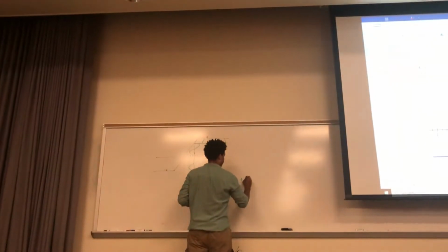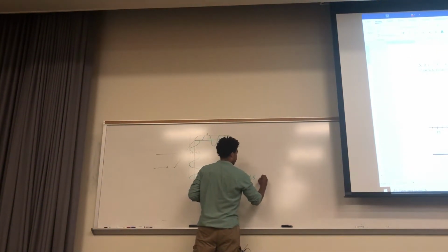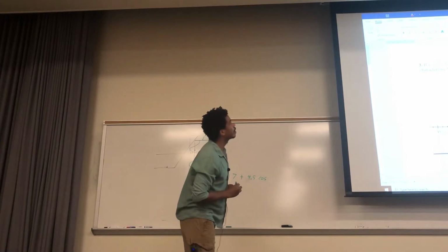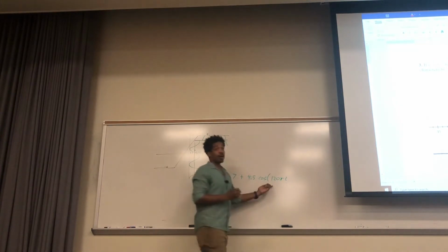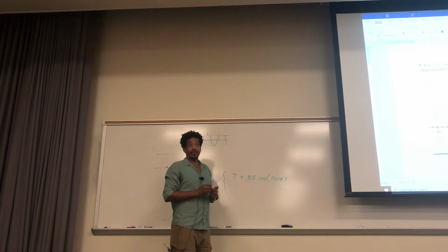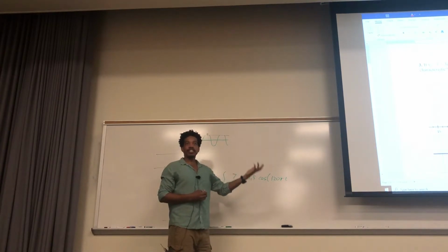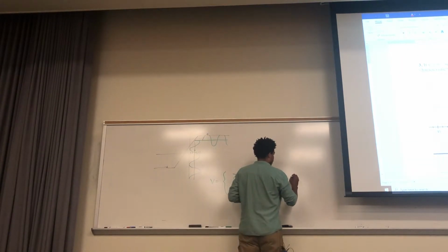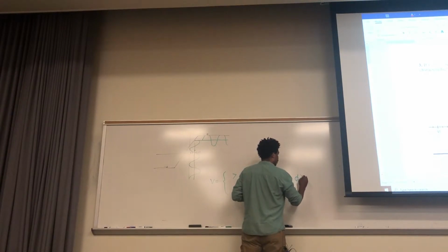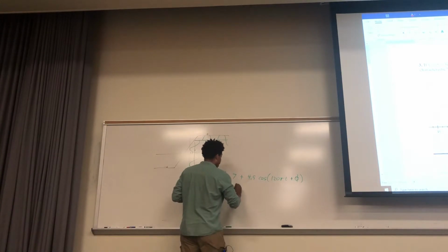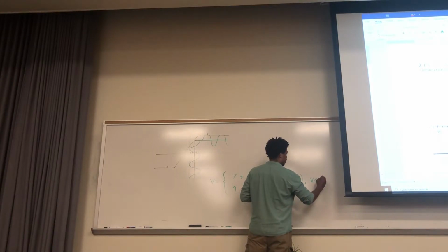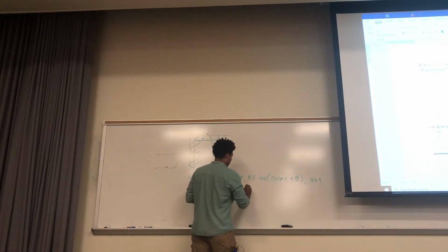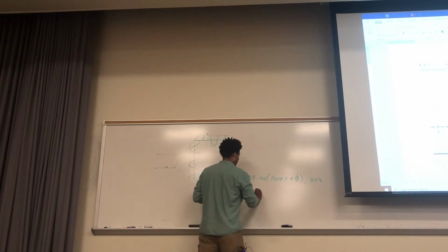So 7 plus 4.5 cosine, what frequency do we have? 120? 120 pi. Oh, and it's going to be off by phase, right? It might be, because we talked about this little lag, because everything inside of an op amp has like RC. So it's going to be a little bit of phase. So let's throw that in there. Or it's going to be 9. So it's this for voltage less than 9 volts, or it's 9 whenever voltage is greater than 9 volts, because it's clipped.